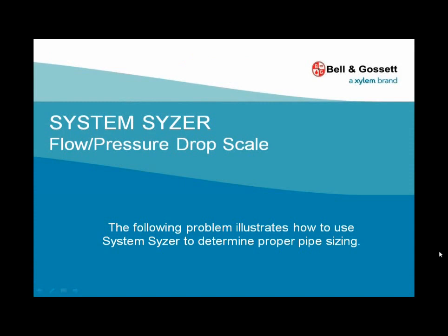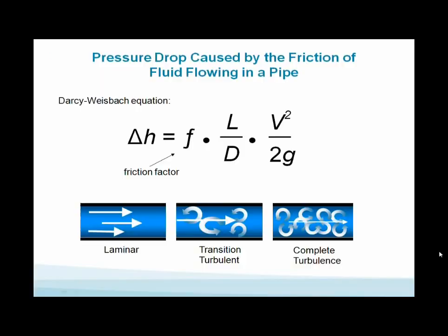Let's just keep going now. We've been through the first scale to kind of see what's involved there. Let's go to flow and pressure drop, see what's going on. First of all, I've got the GPM now from scale 1. What size pipe do I need? What is the velocity going on? What is the pressure drop? Well, this is the formula from ASHRAE and from research.